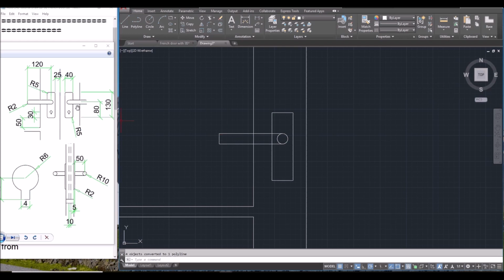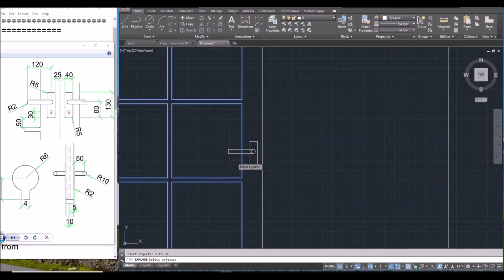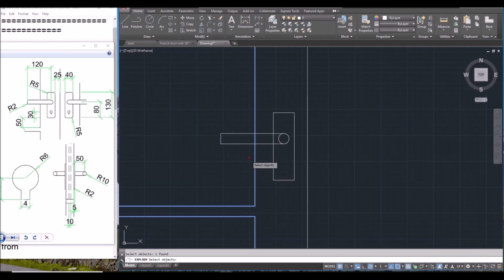Okay, and let's see, I will also need to trim this one. So first I will type X to explode the rectangular array of the window. Okay, X, select it, spacebar to finish, and I type TR for trim and spacebar twice, 1, 2, and then click upon in the middle, move it horizontally like that. Okay, spacebar to finish. Now let's do some fillet.